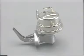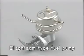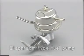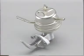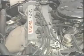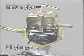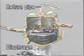The fuel pump draws out fuel from the fuel tank and sends it under pressure to the carburetor. The diaphragm type fuel pump shown here is the most common type of fuel pump used with carburetors. The diaphragm type fuel pump of the 4AF engine is installed on the engine block and is driven by a cam on the engine's camshaft. The fuel pump has a diaphragm in it and a pair of valves which act in the opposite direction from each other. These valves are actuated by the reciprocating movement of the diaphragm and feed the fuel to the carburetor.